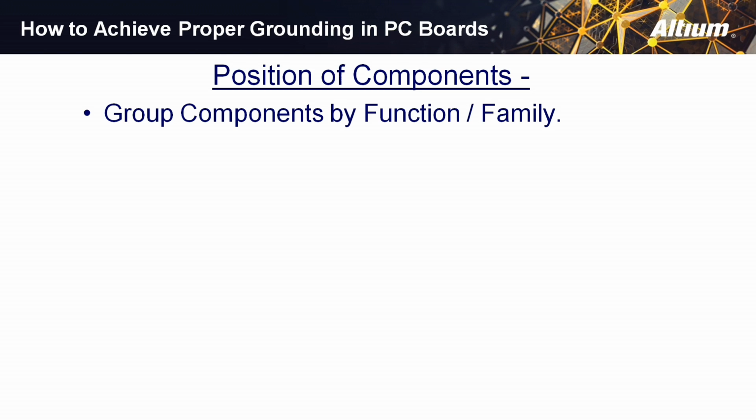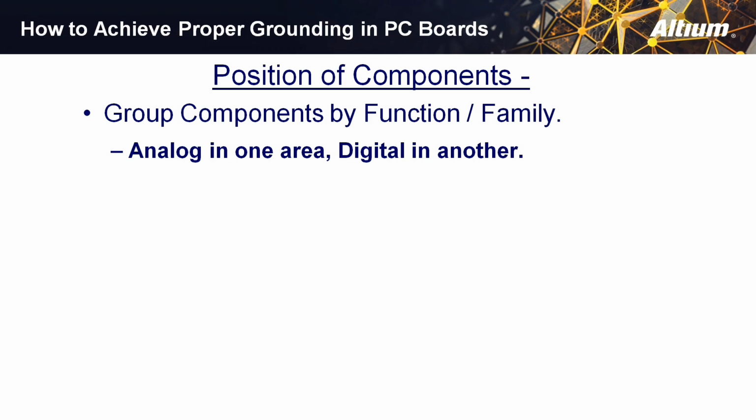On to a slightly different tack. One of the things you want to make sure you do on your board is to group components by function and by family. Analog in its own area, digital in its own area. Not intermingling between the two. You don't want digital signals routed next to analog signals. You want analog to be contained in one area, digital in another.